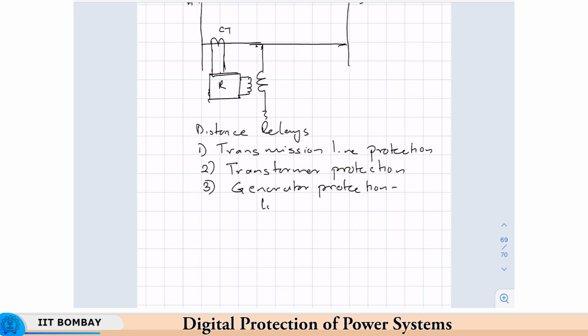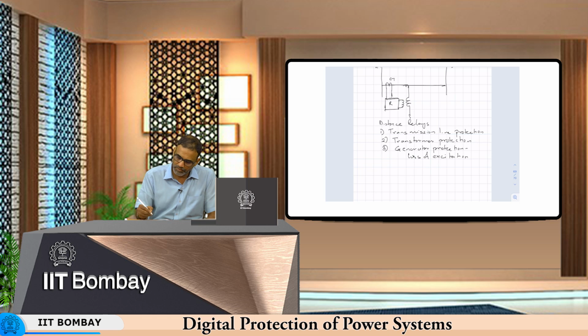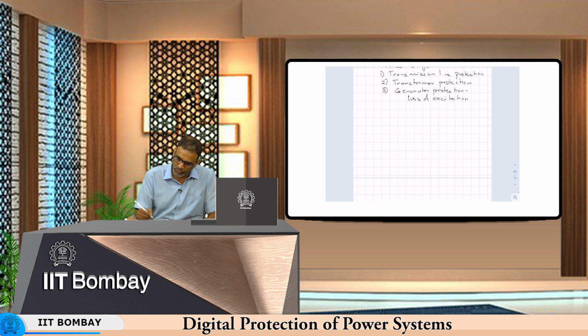Of course, the most accurate would be differential relays, but there is also a higher cost involved. So a majority of transmission lines will still use distance relays compared to overcurrent relays.